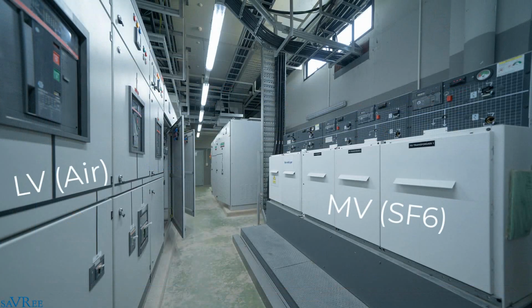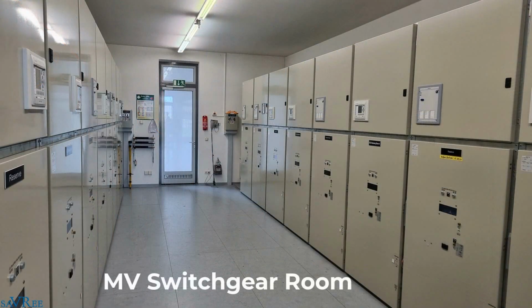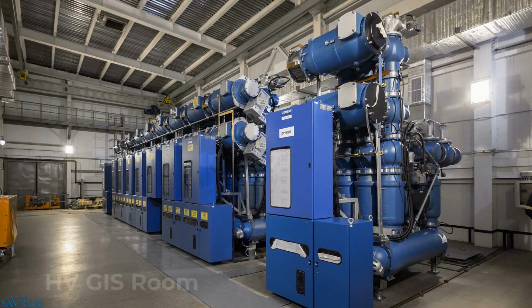You don't need oil, vacuum, or SF6 to extinguish the electrical arc at low voltages. When we're looking at medium voltage switchgear, that's when we begin to use oil type switchgear, vacuum type switchgear, and gas insulated switchgear, such as SF6. If we go into the high voltage range, you're more likely to encounter gas insulated switchgear.